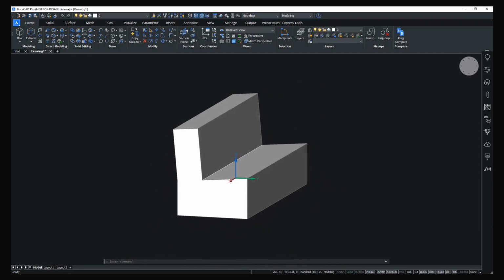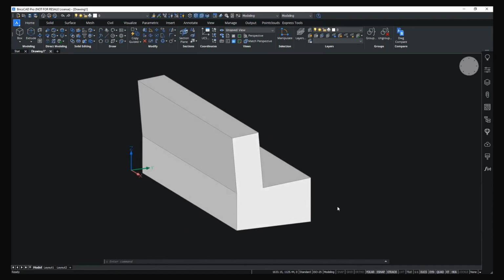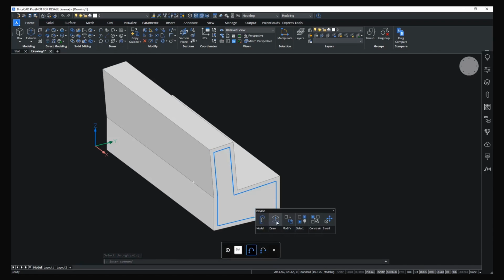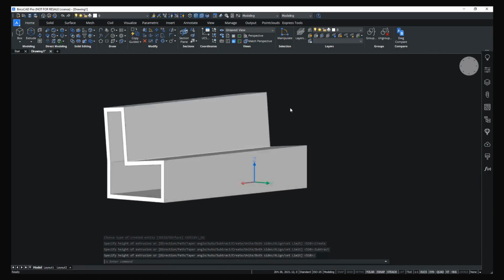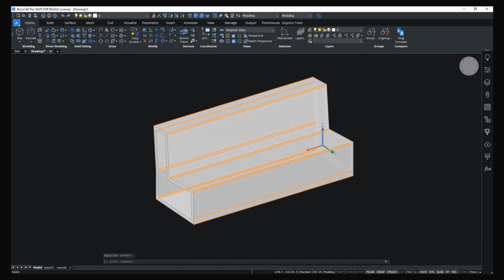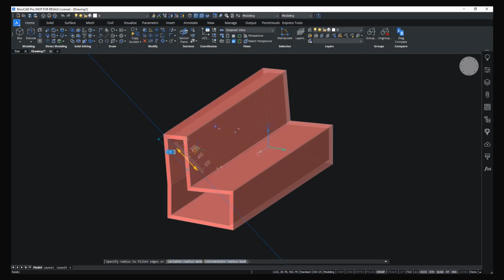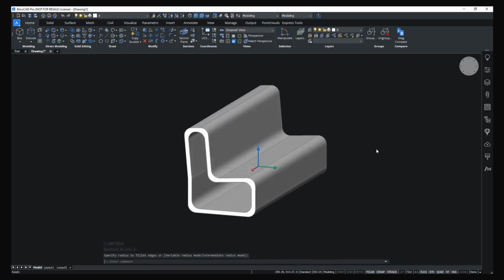In case you hadn't noticed, I'm currently building a simple 3D model of a bench, and I will just do a few more steps to finish this bench. So I'll create this offset here, and then extrude this volume so I get a hollow solid like this. And I'll add some fillets to the edges so that people don't cut themselves when they go sit on it, and also just to give it a bit more of an organic look, like this.